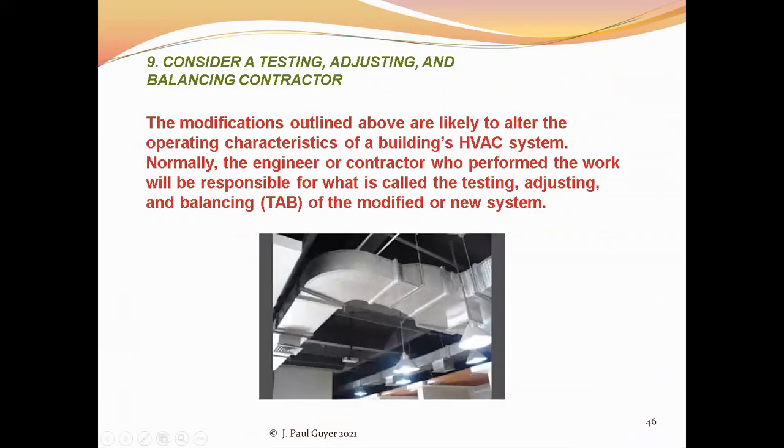And then the point that I alluded to earlier: on an older system it can probably be appropriate and effective to employ a testing and balancing contractor if you're undertaking to retrofit an older existing system, so that you know what you're dealing with as far as what the system is actually delivering to the different occupied spaces.